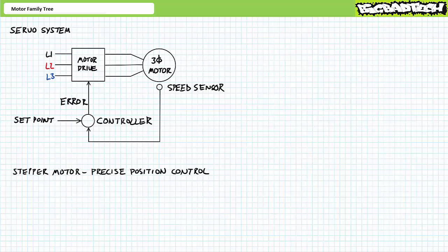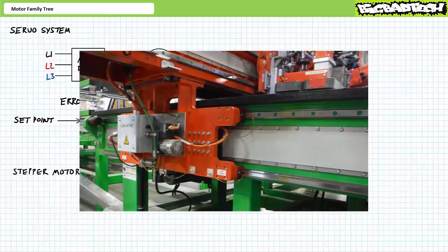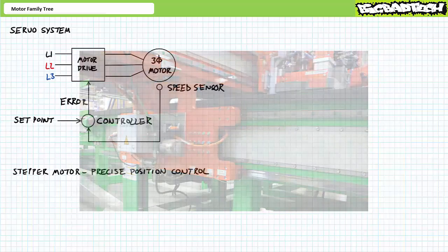Finally, I should probably mention that not all motors feature an external stator wrapped around an internal rotor. And believe it or not, some designs include an external rotor wrapped around an internal stator. As an extreme example of the variances in construction you may encounter, consider a linear motor that unrolls the stator in a linear fashion called a platen, and the rotor, called the reaction plate, slides linearly along it. It still uses motor theory, however it moves linearly rather than rotationally. Does it match my earlier definition of a motor? Not really, but it's definitely not a solenoid.